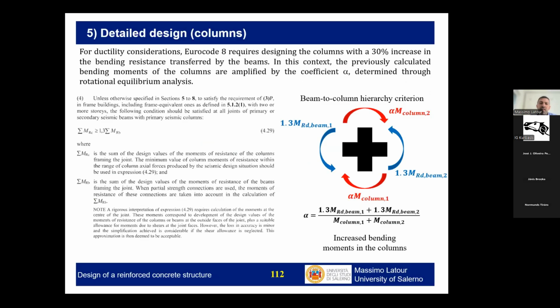So the action in the column will be derived by hierarchy, magnifying the design forces, the design bending moments, by a factor equal to alpha.